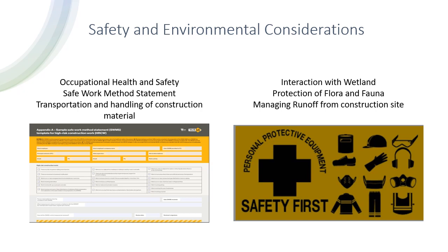From the environmental point of view, minimizing the construction footprint is very important. Controlling measures like establishing no-go zones, using sealed barriers and sandbags to control the runoff from the construction site, and proper collection of construction waste and disposing of it safely is the main way to avoid impact on the environment.